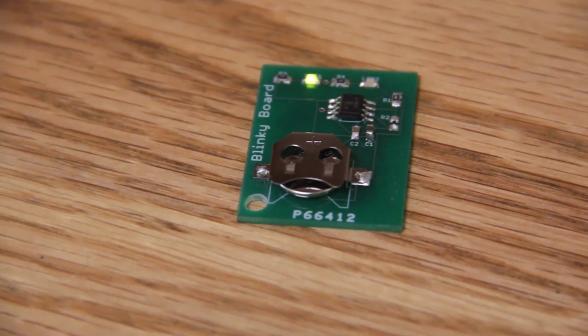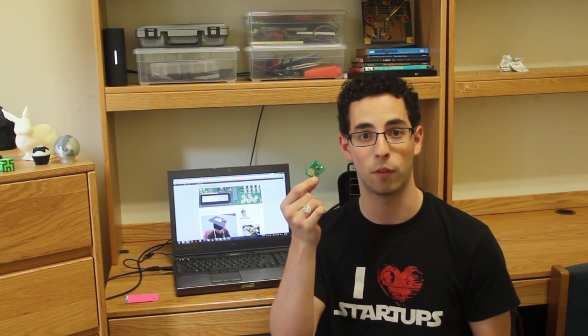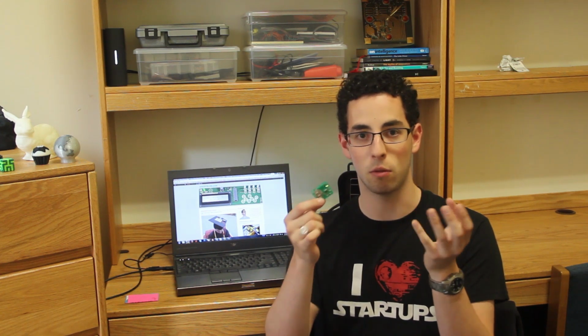Basically, it's just a simple little watch battery, a 555 timer, some passive components, and some LEDs that blink back and forth. So we'll walk through first how to do the schematic of this, how you wire all the parts together in a virtual fashion, then how you actually do the layout on the board, and last we'll talk about how you would get the PCB manufactured. Okay, so let's jump into working on the schematic.